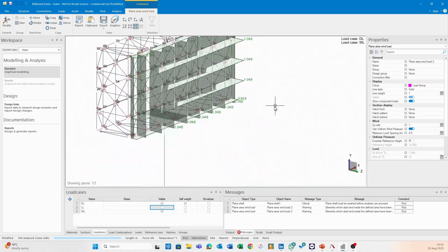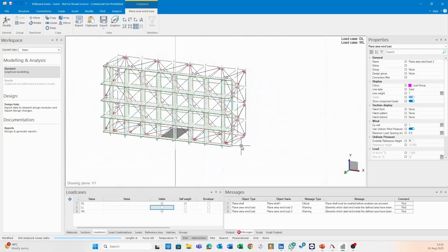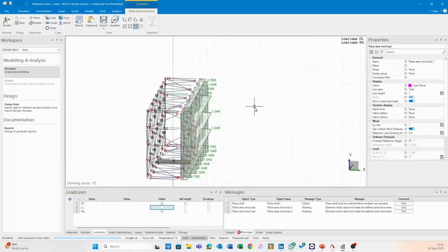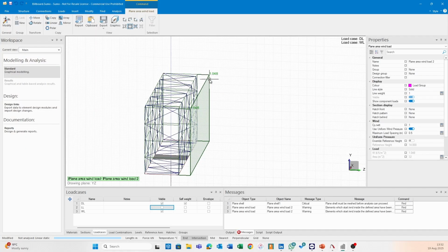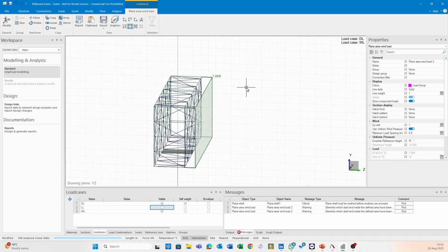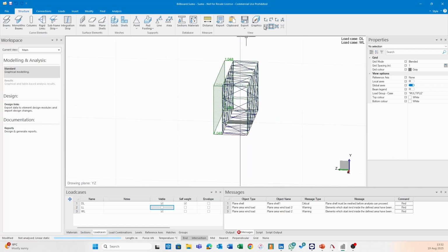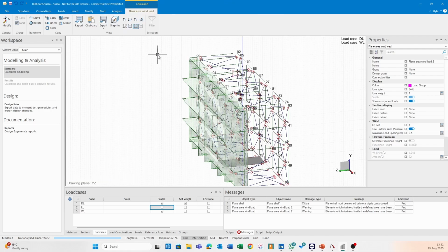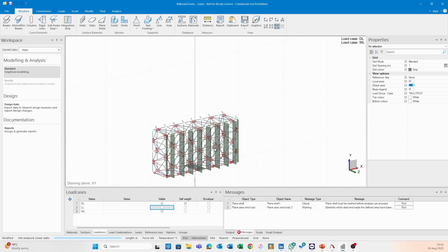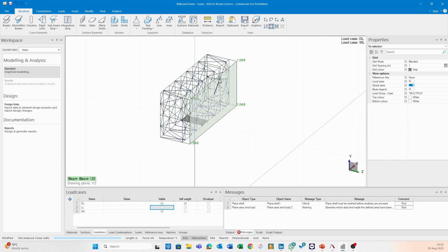All right, that's great. That's new for me as well. I've never tried to impose them over one another. The only thing to be cognizant of here is the magnitude of this pressure, because you've now got double that over that area. So that is just something to keep track of. For this particular scenario, I'm going to delete one of them. But I hope that you are now confident in how to apply that wind load.